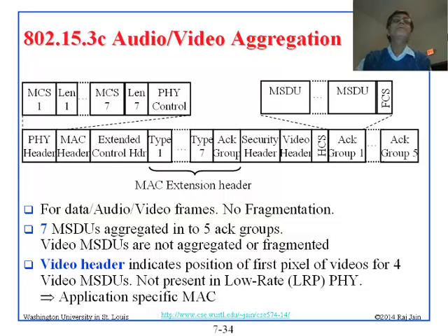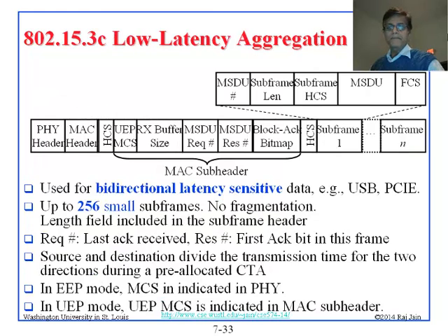So you were mentioning that the subframes were small. Any notion, like in bits or bytes, how much that is? How much is small? Yeah. Oh, small could be 1 byte. I mean, see, the thing is, unlike Ethernet, if you want to send 1 byte on Ethernet, you have to make it I think 48 bytes or so with 16 bytes of error check. 64 bytes is the minimum Ethernet size, right? Here there is no minimum size.